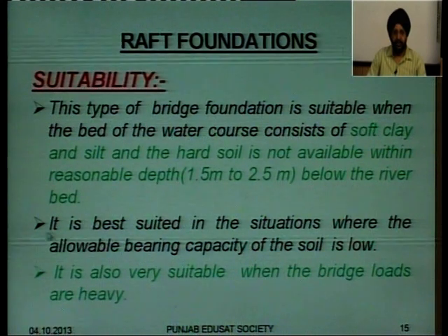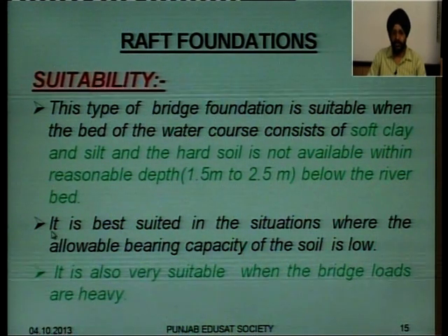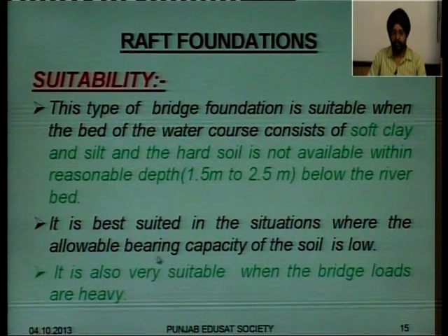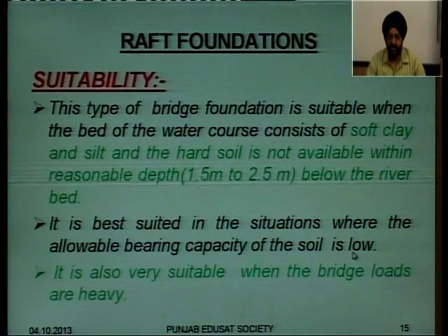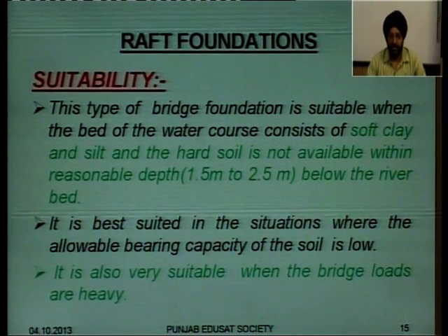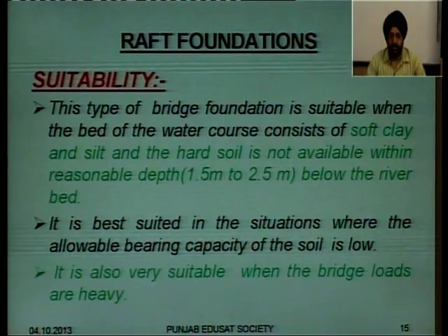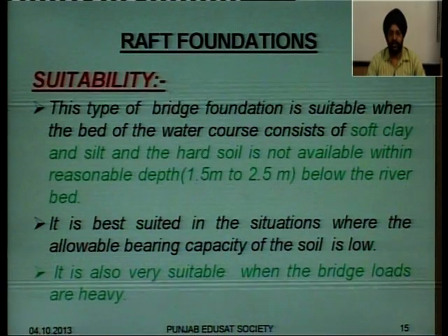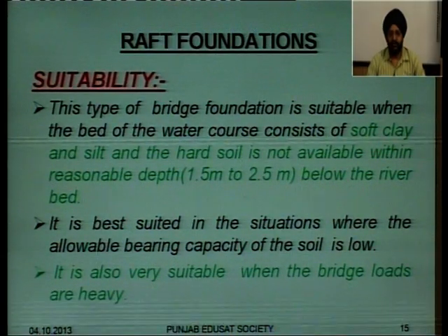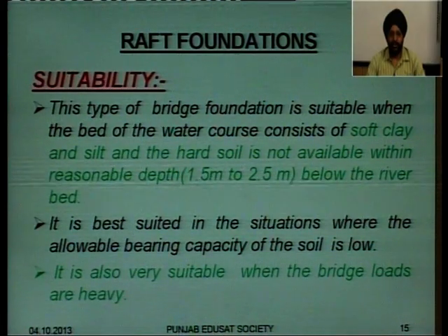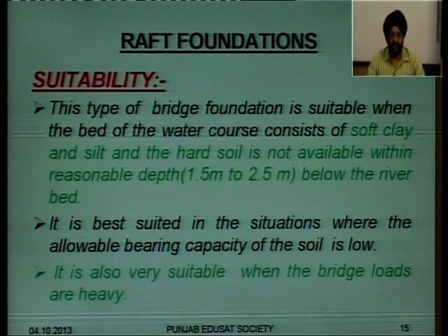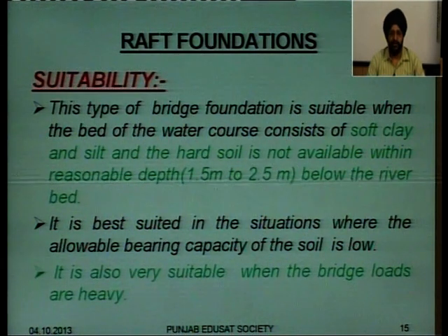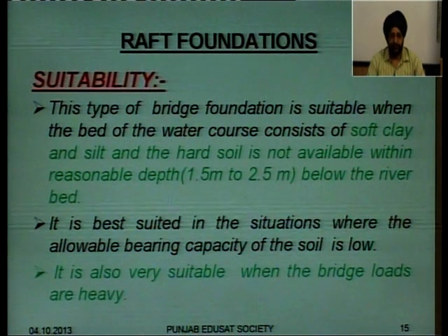Secondly, these are best suited in situations where the allowable bearing capacity of the soil is low. The second suitability of raft foundations: whenever the allowable bearing capacity of the soil is on the lower side, and the depth is up to 5 or 6 meters, raft foundations are the best option for bridge foundations.